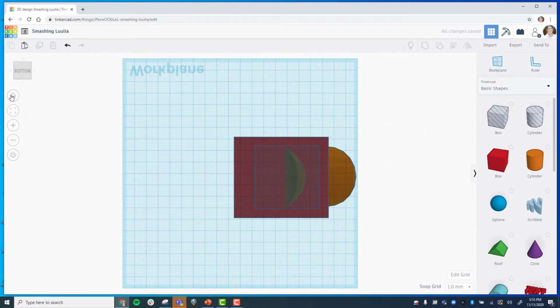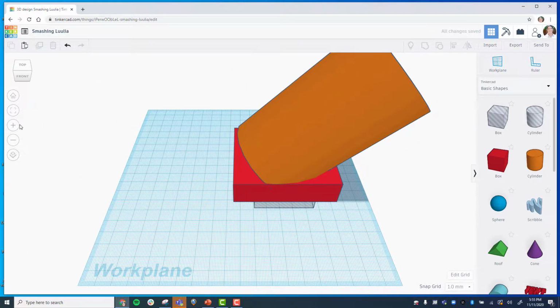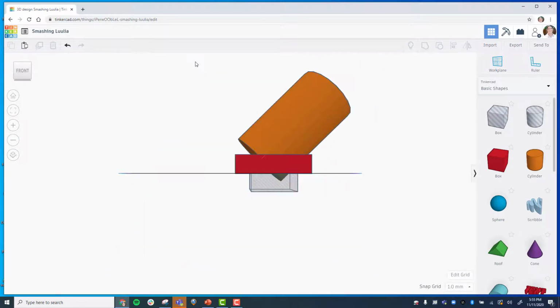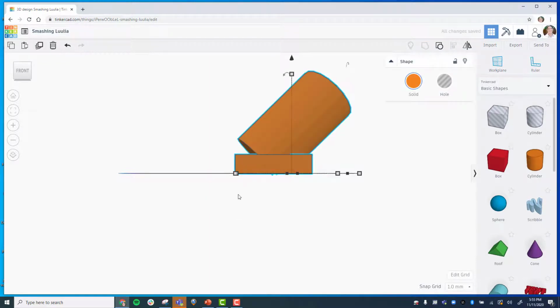And we'll zoom out. So now what we're going to do is left click and drag all objects. You can tell that all objects are selected once there's a blue halo around each object. And now we're going to group them and watch what happens. The base that was protruding with the cylinder below the work plane is now gone, and now both objects are the same color, which means they are now combined. So go back to our regular view and zoom out.